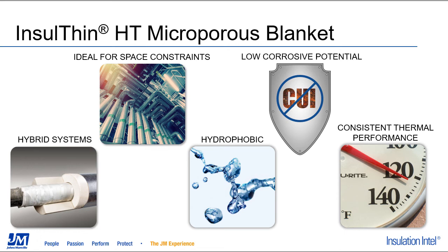It does naturally have a very low corrosive potential, as you saw from that very early CUI data that I reviewed. It's very similar to that of DI water, so even though it does not have the XOX corrosion inhibiting package, it has very good corrosive performance. It's excellent for hybrid application systems, used in combination with mineral wool, calcium silicate, or perlite, to possibly mitigate some of the limitations that other products may have.